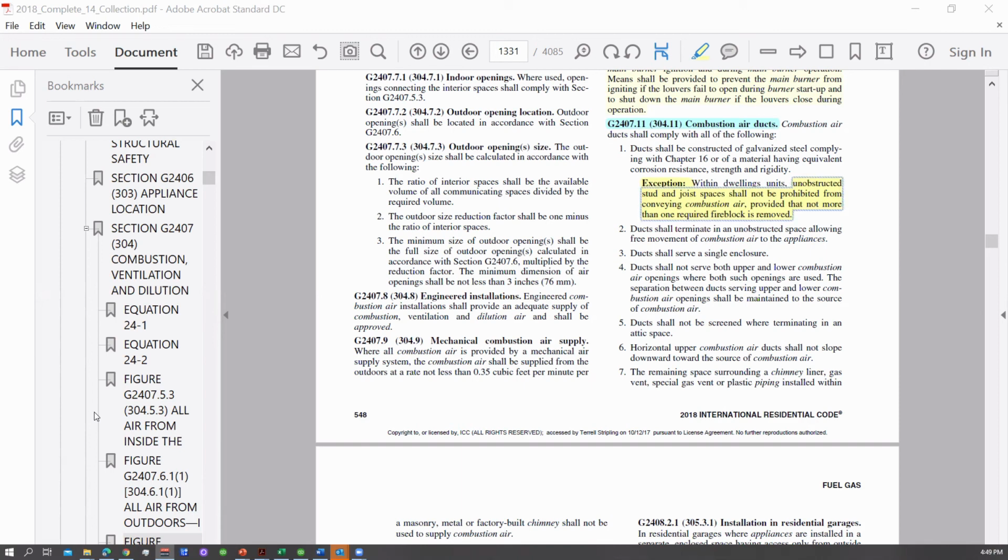The building contractor called me. We approved the drawings, and we approved the outside air with the louver in it. I had a meeting with the energy rater, and I had to bring in my mechanical code and my energy code. I bantered with him a while, and I said, number one, this is a safety issue. We will not block the combustion air in the building envelope to the exterior. That will remain there. That's a function of the mechanical code.